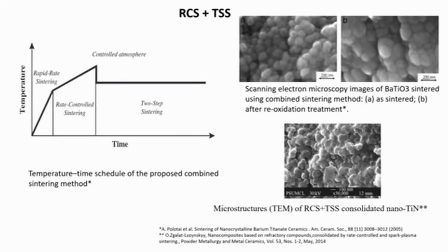Rate control sintering enables control of microstructure evolution during sintering because of a feedback existing between densification and heating rate. The first stage of heating during rate control sintering follows the methodology of rapid rate sintering. It is well known that open porosity effectively impedes the grain boundary migration. During the final stage of sintering, around 90% of theoretical density, here you can see,